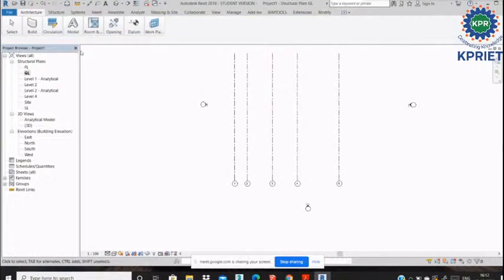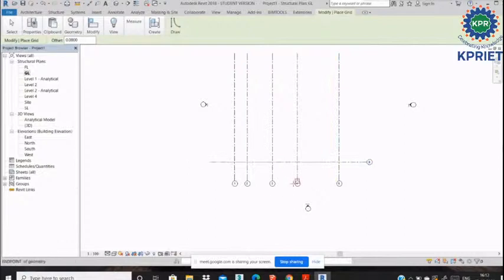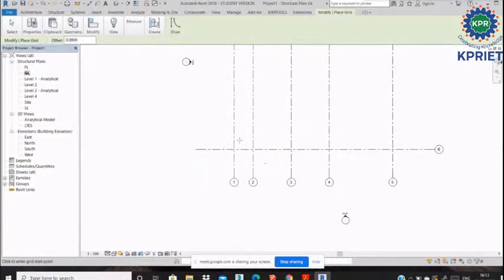Okay, next, this is the width portion, and I need the length portion. Simply do the same. Go to grid line, then go to draw grid line. Then I need this to this grid line, in the same way. Pick lines. This is 3 meters.